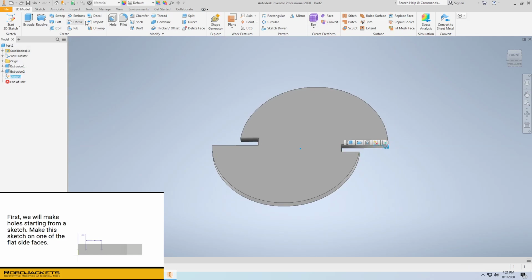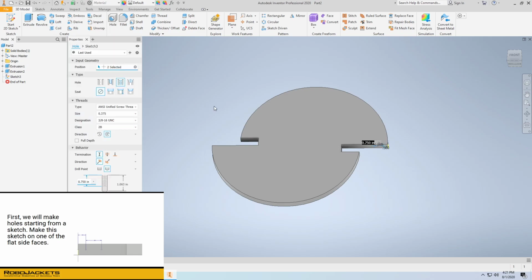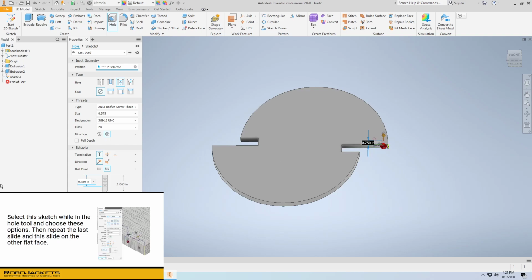And by simply selecting the sketch and choosing hole, you now have holes started at those points. For the settings on these holes, we'll want 0.75 deep, which we have. Size 0.25. So let's go ahead and edit that here. There we go. Make sure these updated correctly. So this guy looks like he got changed. Set him back. Here we go. And actually, the hole goes deeper than what we want tapped. So we'll input here. There we go.